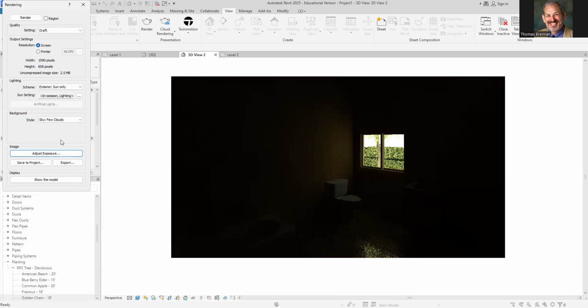Yes, sir. Grass. To make grass, go to floor, then floor architectural, and hit your types. Under types, I've actually got earth. When you go to earth, you zoom out and make a big rectangle like I did. Choose your rectangle tool and make a big rectangle. Go ahead and close it off. Yeah, good, and click. That's it, hit the green check mark, and take a look at it in 3D.